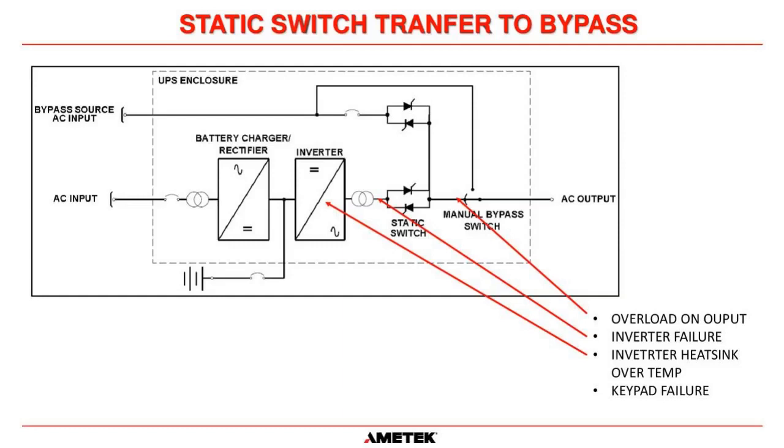We also look at inverter heatsink temperatures and over temperature at the actual inverter bridge. Heatsink temperature is just monitored. Many of you have seen this, the little round, they call them snap discs or something like that. They're about the size of a nickel with two little leads sticking up and bolt right on the heatsink. It's a bimetal strip that closes when it gets too hot.